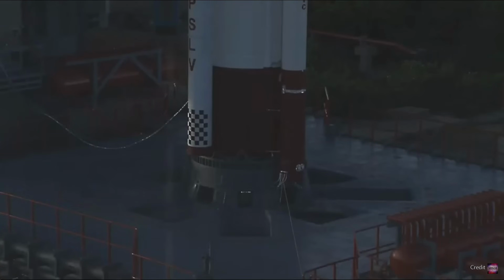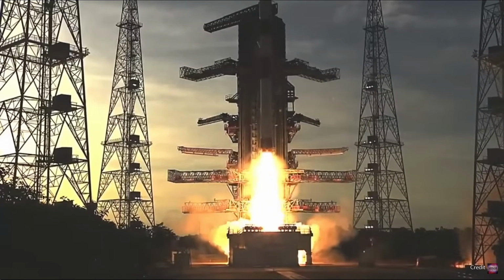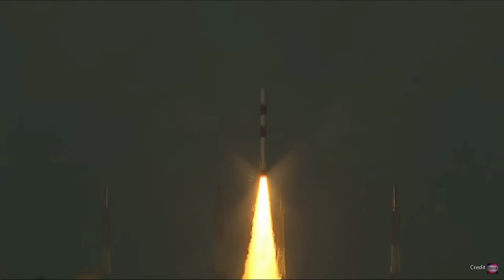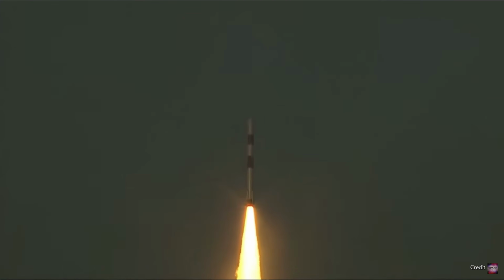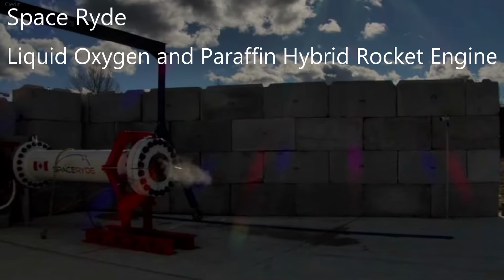The problem with solid rocket motors is that they are not easily throttled. We talked about the internal geometry, allowing variable thrust, but once you light one, it's pretty much gone. You could blow out the sides of the combustion chamber, or dump a bunch of liquid nitrogen down the core, but now you're adding mass and complexity. You might as well go with a hybrid rocket motor instead.